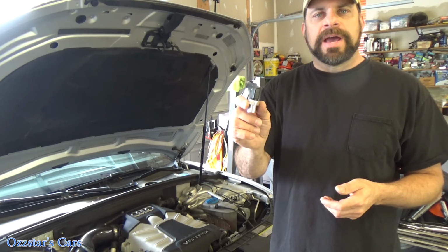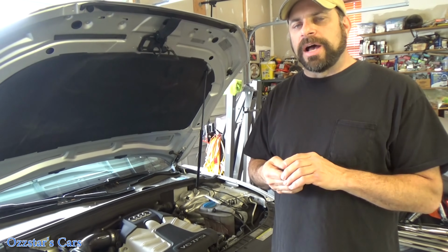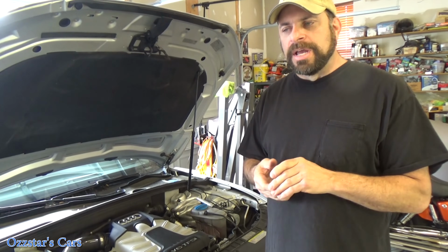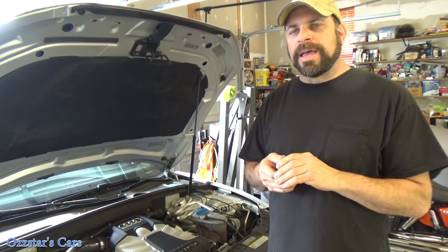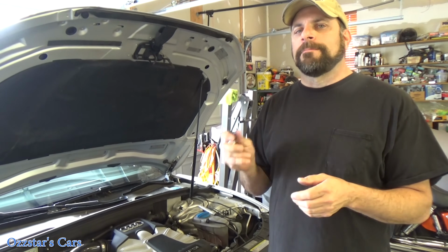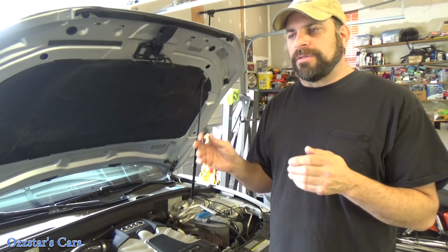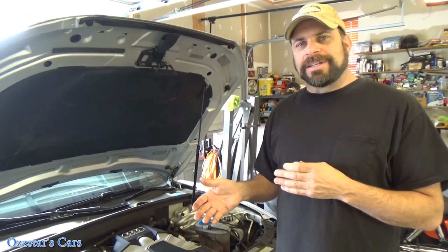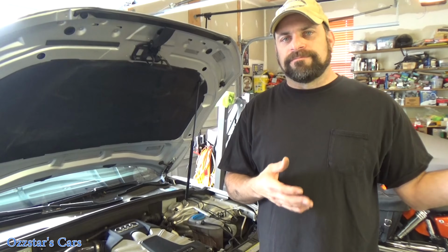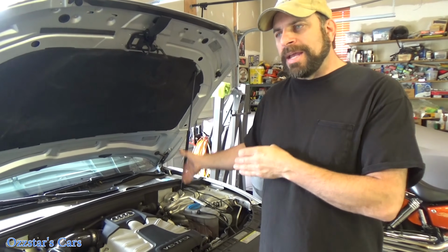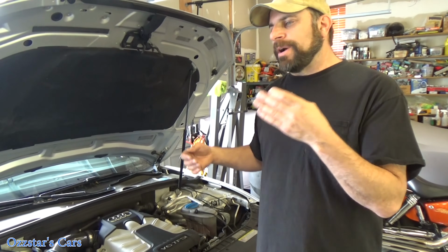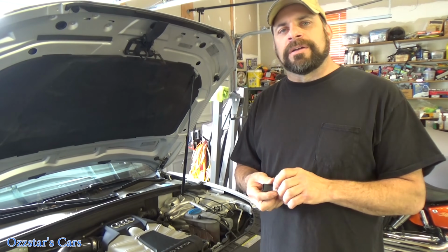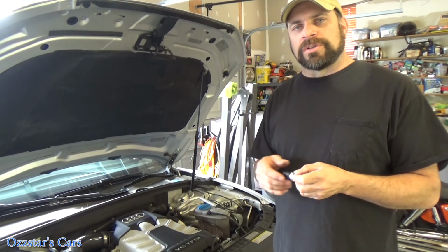If you have a bad switch, the most effective way to diagnose it is to have one of those powerful scan tools. If you don't, keep in mind that a regular little code reader may not give you the codes that we looked up, like that 256 code. And if you don't have a manifold gauge set, you may not know if it's the low refrigerant. You might not know if it's this. You can start playing the guessing game. I can't figure out any other way to diagnose it other than what we saw there.